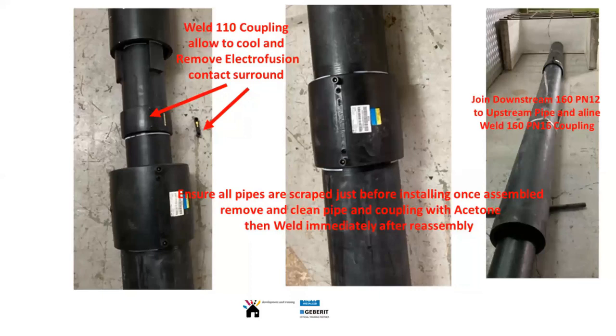Once the weld is cooled, and the cooling is the most important part about HDPE welding. What happens in the welding process is that as the heat gets generated through the coupling and the pipe, the two polymers start to melt and get soft. And once they are at the 220 degrees and they've got the correct soak period, the weld will stop, and then they have to cool down. And it's in this cooling down process that the weld actually happens. That is the most important part of it: the molecules start to contract and go back to their original state. And that is what makes sure that pipe is going to be a perfect joint and never come apart.